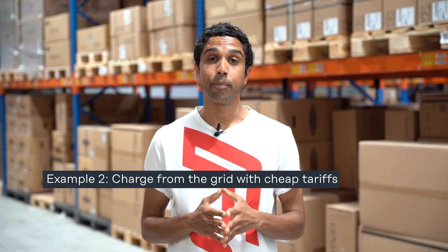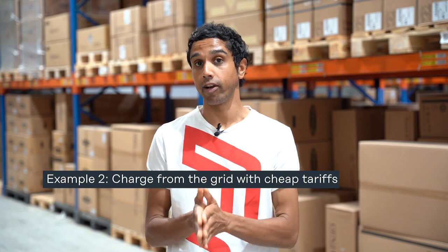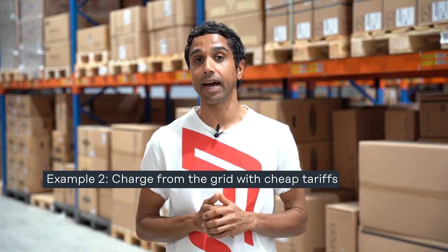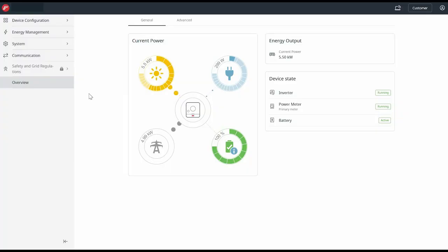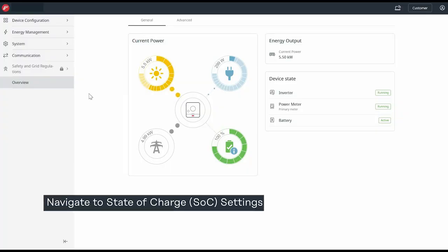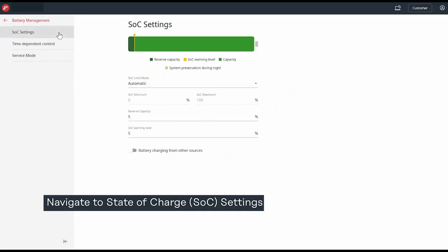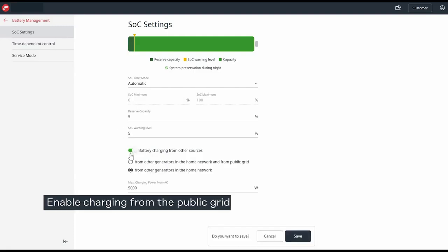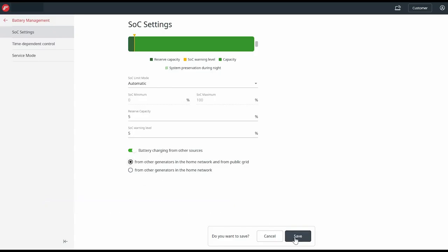In this second example, we're going to enable charging from the grid when you have access to cheap or free electricity during the middle part of the day. For this function, we want to allow charging from the grid, so we need to navigate to the state of charge settings, which are located in energy management, then battery management, then SOC settings. Tick battery charging from other sources, and select the option that includes charging from the public grid. Then click Save to apply the settings.